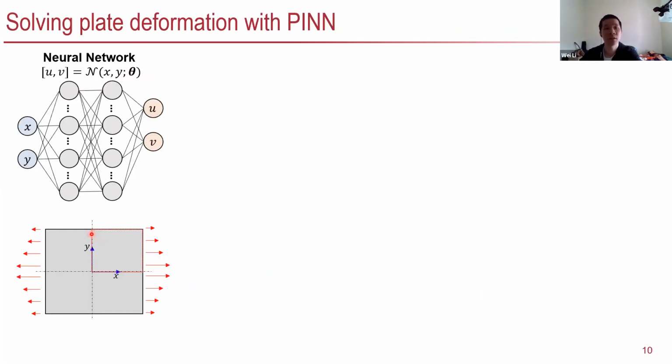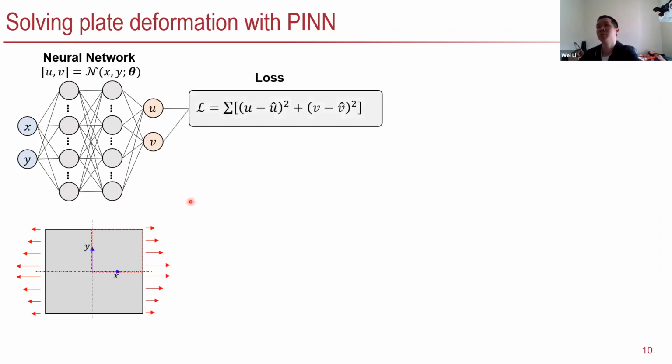Then we try the first case of a plate deformation. So this is only a plane stress tension with some non-uniform stretching force. For conventional or purely data-driven methods, we may need to know the outputs or some exact solution of this. For example, in this case, the displacement fields. And then we try to minimize the noise so we can have a good fit of the exact solution.